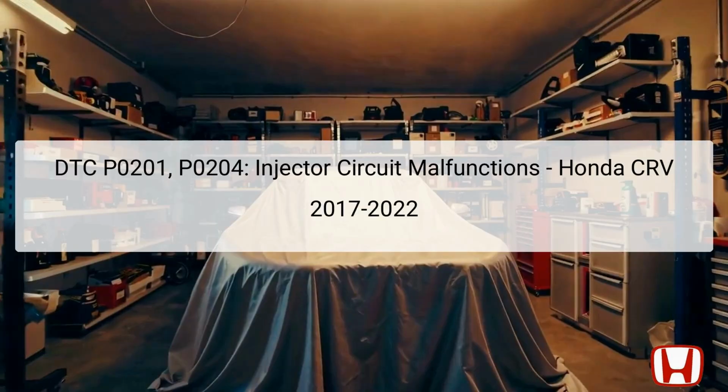This presentation covers diagnostic trouble codes P0201 and P0204, which pertain to injector circuit malfunctions in the Honda CRV models spanning from 2017 to 2022. DTC P0201 signifies an issue with the number 1 cylinder injector circuit, while P0204 indicates a malfunction in the number 4 cylinder injector circuit. These issues can arise from a variety of factors, including wiring problems, relay failures, or sensor